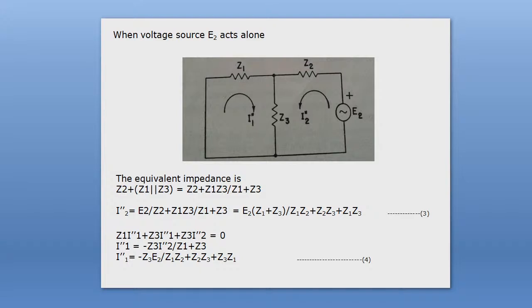Even if your circuit consists of AC source or DC source, or resistances, or resistances and capacitance, I mean real valued element or complex valued element, you can solve it by using the concept of superposition theorem. You just calculate the current components for individual sources, then you sum up the values of those current components you have obtained for individual sources. So you will get the ultimate values of current components. So this is one approach you can use to solve your problem.